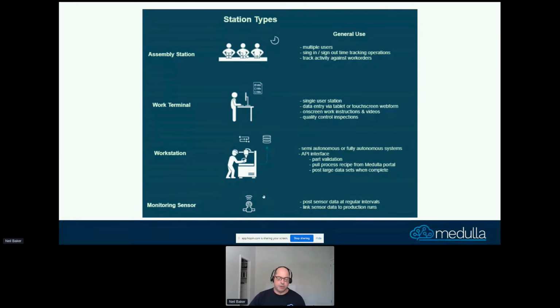And then you have just remote systems that are sitting there, environmental monitors, temperature, humidity, such. Perhaps a couple of other stations that are just sitting there, just logging things, not connected to any particular production flow, but they're logging things to make sure that the environment is within a certain set of specs. If that alarm goes off, you want to have that traceability down to your production line so that potentially you can either halt production for the period that its sensors are going off, or at least have that traceability. So if you're looking at why product failed, you can link the time and date to those events.